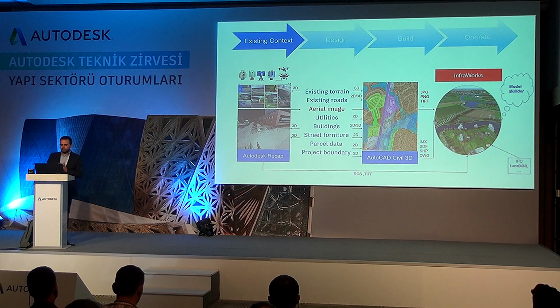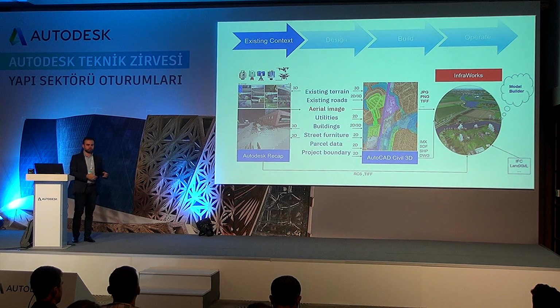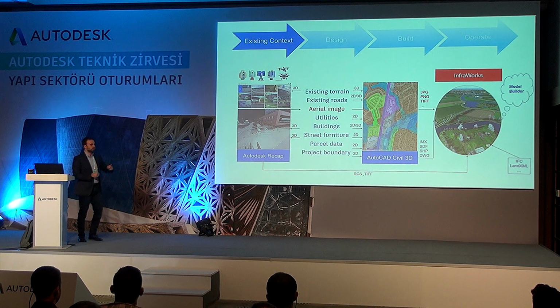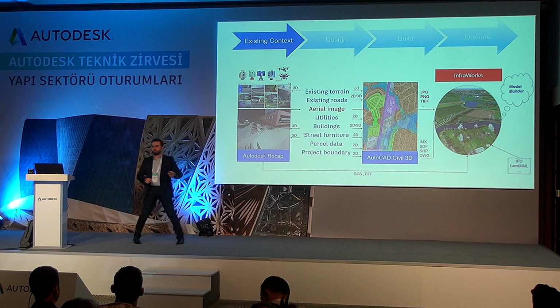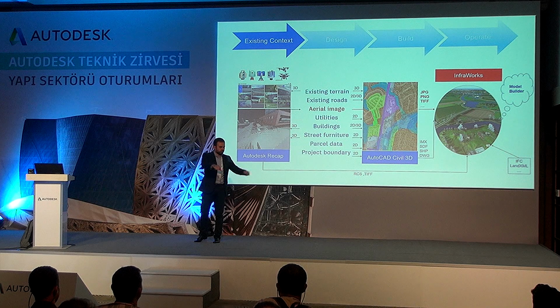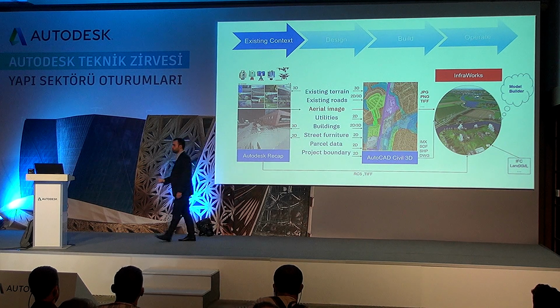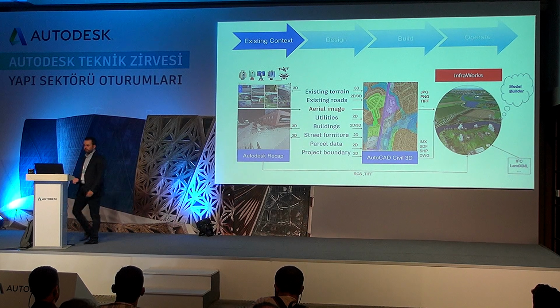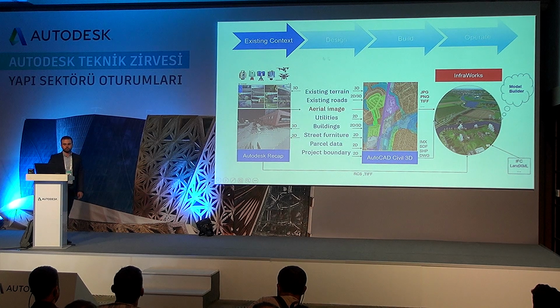So nowadays, instead of having the traditional workflow, as I mentioned in my previous session, having surveyors on site, putting a total station, and having another one on the other side, carrying like a pole or a column, and they start to take points, just random points, the new trend is using laser scanning. And this laser scanning is very powerful.